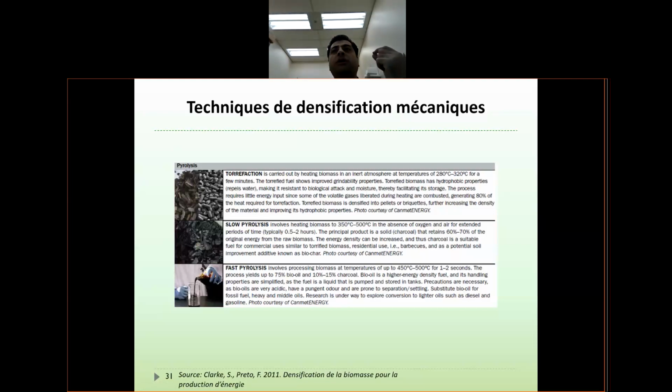But what about a single particle itself? When we talk about a single particle, not a group of particles, you have two definitions: grain or particle density and skeletal density. If your particle is not porous, these two are similar. But if your particle is porous, like the shape here, you have empty voids inside the particle itself.